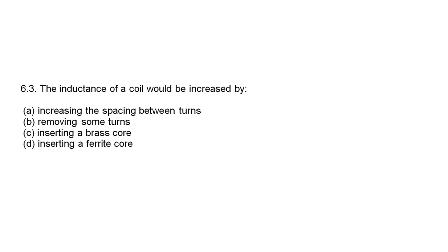Question 6.3, the inductance of a coil would be increased by increasing the spacing between the turns. No, that would decrease the inductance. Removing some turns, that would decrease the inductance.